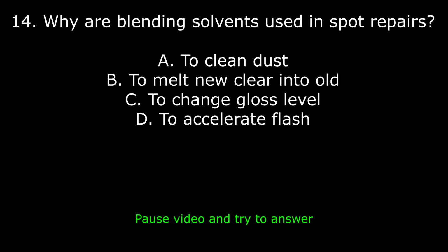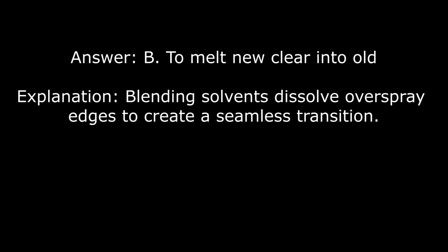14. Why are blending solvents used in spot repairs? A. To clean dust. B. To melt new clear into old. C. To change gloss level. D. To accelerate flash. Answer: B. To melt new clear into old. Explanation: blending solvents dissolve overspray edges to create a seamless transition.